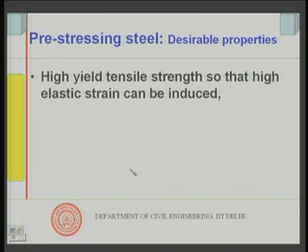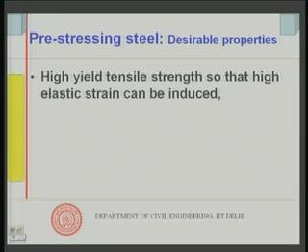Let us quickly discuss some of the usage and some of the steels you use, in cases like pre-stressing steel. What are the desirable properties of pre-stressing steel? It must have high tensile strength. When do you use pre-stressing steel? I might have mentioned this in connection with concrete. Concrete is weak in tension, it is brittle. So, to improve its tensile load carrying capacity, we either reinforce it and use a composite called reinforced concrete. The other way is to pre-stress it